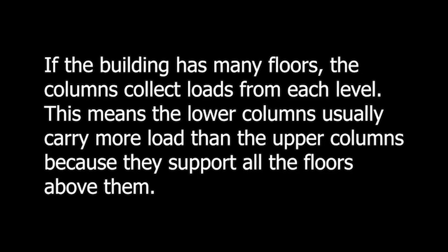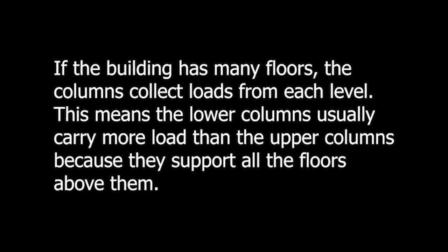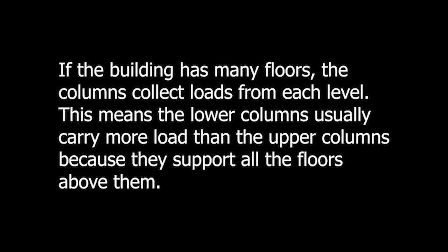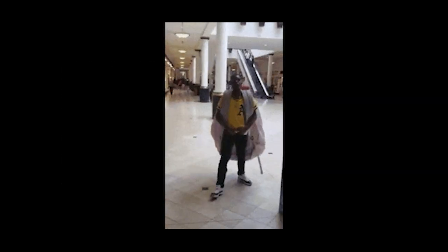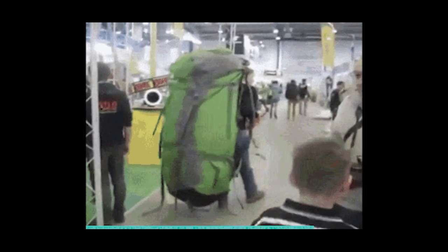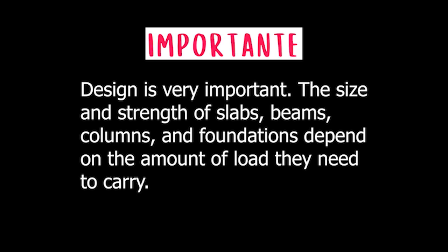If the building has many floors, the columns collect loads from each level. This means the lower columns usually carry more load than the upper columns because they support all the floors above them. Think of it like carrying a backpack. If there is only one book inside, it feels light. But as more books are added, the backpack becomes heavier. The lower columns are like the person carrying the entire backpack of the building. This is why structural design is very important. The size and the strength of the slabs, beams, columns, and foundations depend on the amount of load they need to carry.